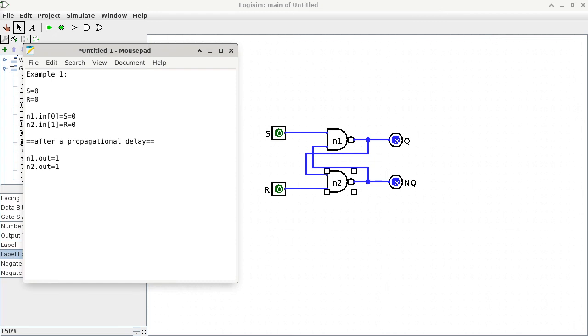In other words, we really do not need to know what the other input pin is, but by knowing just one of the input pins is a 0, we know for sure the output pin is going to be a 1. All right? Now, this is really important. What is important is not the fact that we know now that the outputs of both NAND gates are 1s. The important part is how did we figure it out?